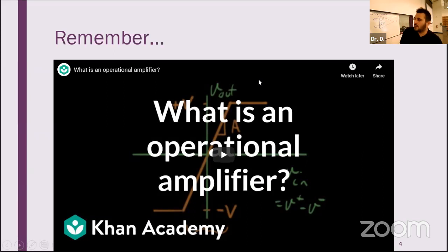So when you ask, do you need to know all of this, how op amps are configured with the power supply and stuff? Not particularly for this class. We're just going to use this. What we really need are the ideal op amp truths that we talked about last time: EB minus EA is approximately zero, and the current coming into the op amp is approximately zero.